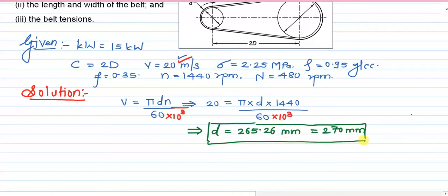Now after that, we know the relationship between the diameter of the pulley and their speed. The relationship is that they are inversely proportional. So if diameter is more, then speed of rotation will be less. So it is actually inversely proportional to the diameter, which means that nd is constant. In simple sense we can write that the product is constant, so ND is equal to nd.